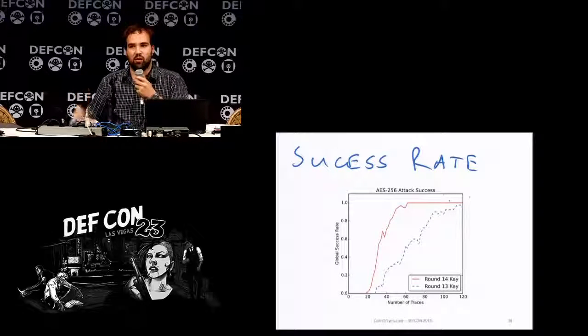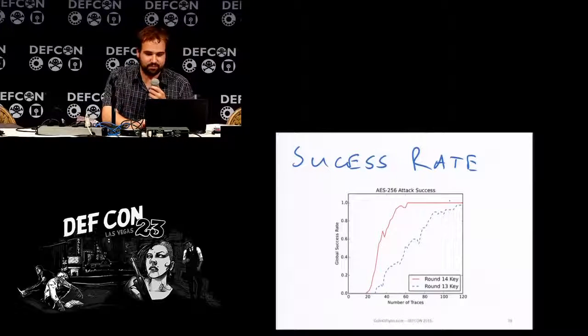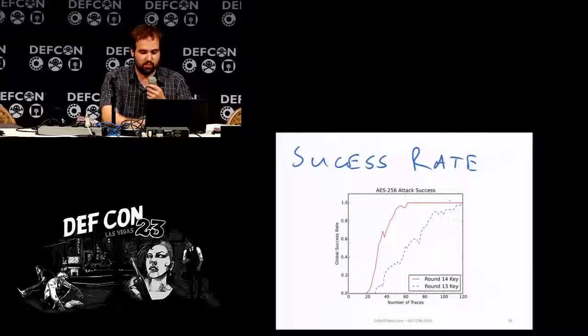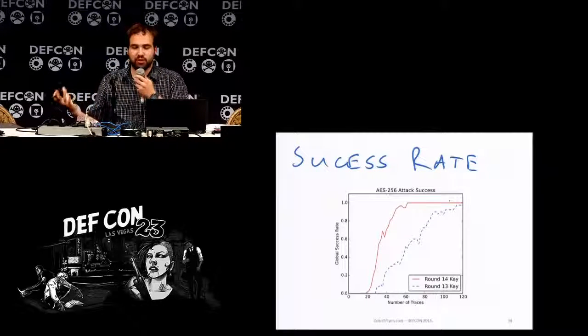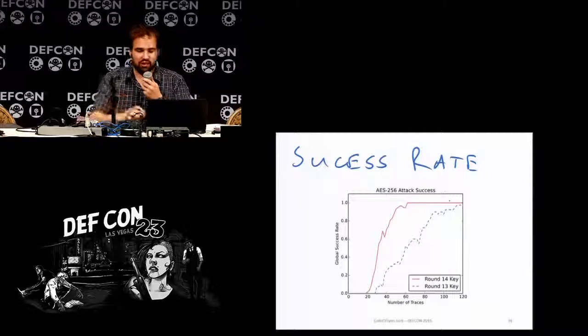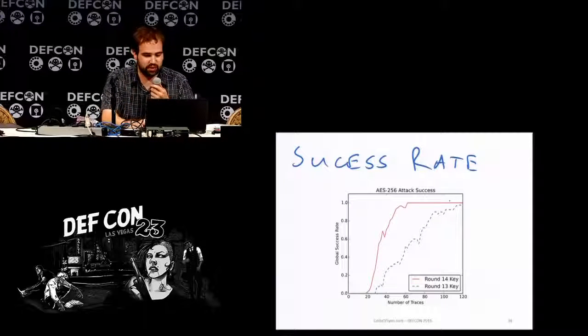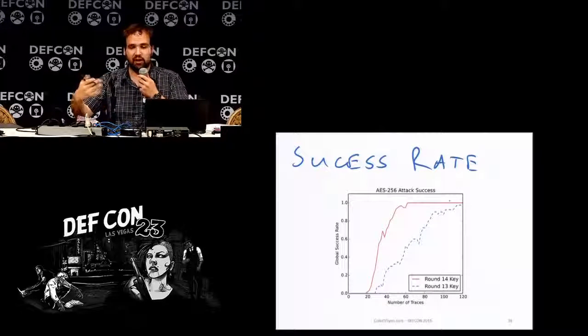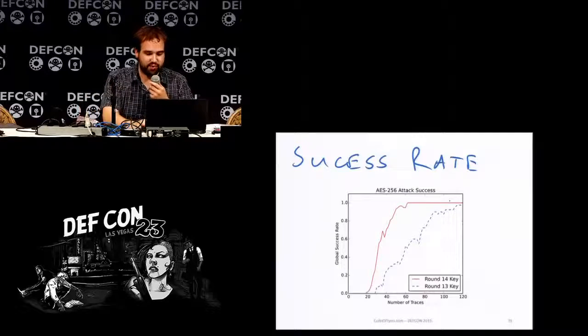So we're talking a bootloader on a micro, and we can send it this data really quickly. This is like 5 minutes of data that you had to capture to break the bootloader. And at this point, we have the full decryption key, so if we had an updated firmware file, we could just decrypt it, because maybe they're trying to hide bugs in their code. They don't want us to reverse engineer stuff like that. Or you could actually send it a new firmware file, and it's going to decrypt it and use that file.